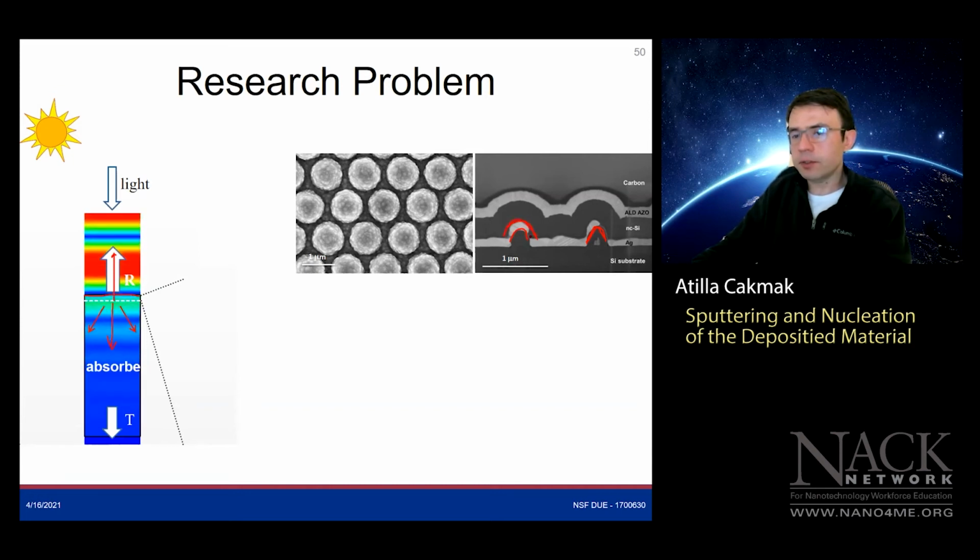It's very difficult to get a good conformal coating. The step coverage, or the thickness of the deposited material on the flat surface with respect to the sidewalls, is not the greatest with sputtering. That's generally the case with these physical vapor deposition tools, and you see we haven't been able to cover this area here.